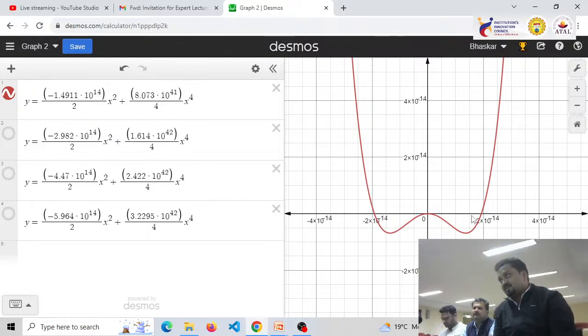Now, if you realize the same thing for a dielectric capacitor, the radius of curvature of that U versus Q will be positive. The parabola will be in the upward direction. Here, for that particular range, the radius of curvature is negative, or I can say the parabola is inverted. So that also confirms the presence of negative capacitance. The same thing which I have done for TFE equals 30 nanometer, I am going to demonstrate for 60 nanometer, 90 nanometer and 120 nanometer.